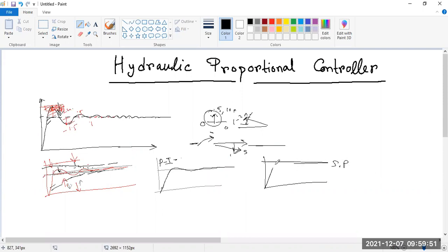So we are applying some integration factor and P factor, but it is going near to the stability line, the set point, but it will never reach the stability finally. So at that moment we are applying some derivative action. Derivative action also works as a damper, but it will just hold it, it will just break this area. Say this is just 1 millimeter here. If we apply derivative action over here, then what happens?